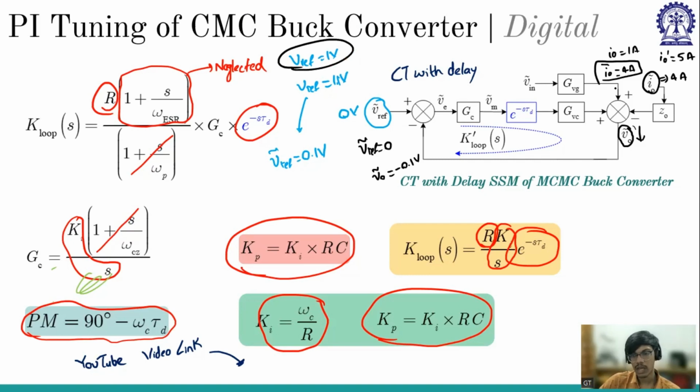So here I0 perturb is 4 amperes, which is the new steady state. And accordingly, it has influenced the V0 perturbation. Now the controller is acting in a way so that this V0 perturbation will come back to its initial state, which is 1 volt. So V reference perturb is 0, also V0 perturb is 0. Is that clear, Rashekar?